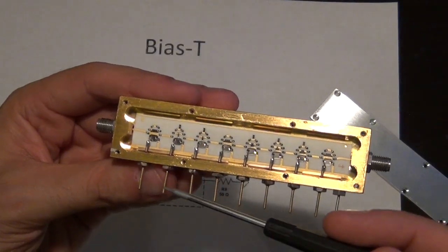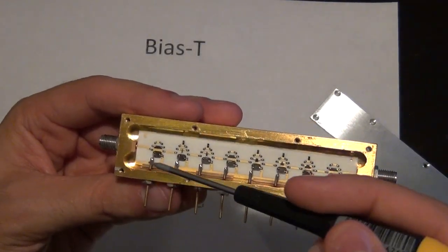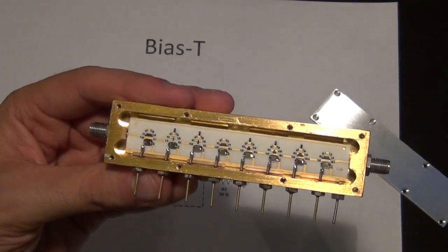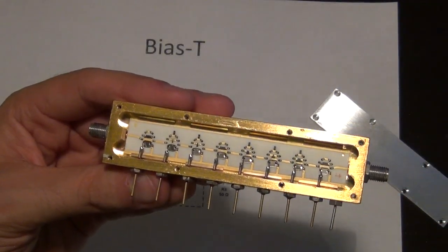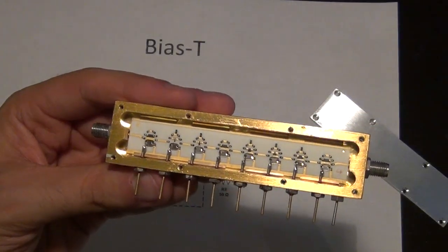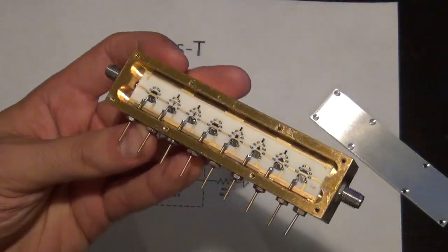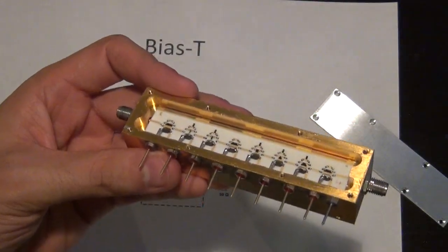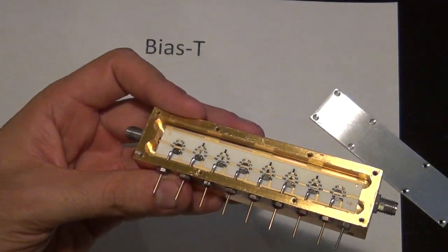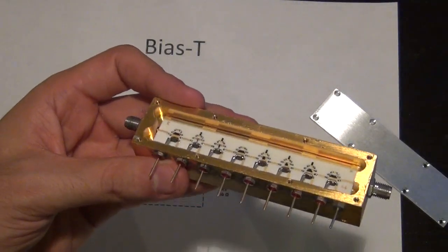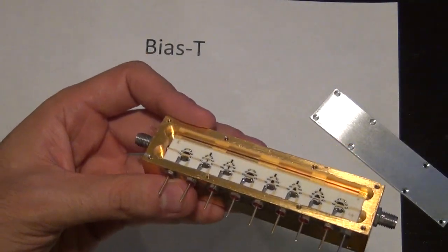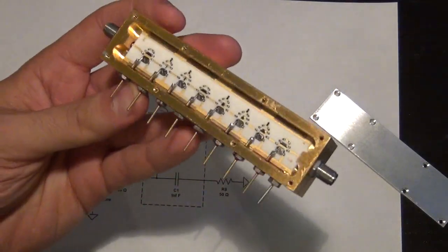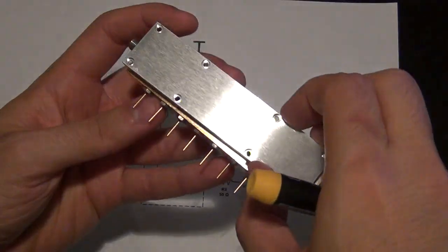It's a microstrip transmission line, and you can see these little black pieces. Those are different resistors. So different ratios of resistors get connected in and out while constantly maintaining a 50 ohm impedance. You can achieve different levels of attenuation. So you can hear this when it is working. If you have a signal source, and you turn the power, let's say you go from minus 30 dBm to 0 dBm, you can hear clicking sounds inside the source. That's something similar to this, where the attenuation is mechanically controlled.